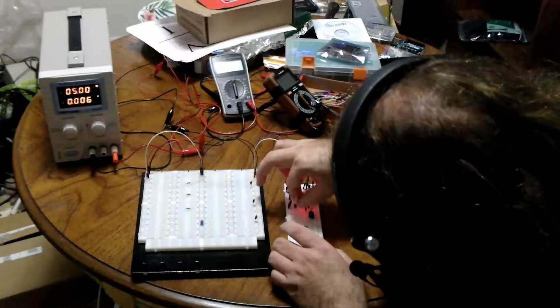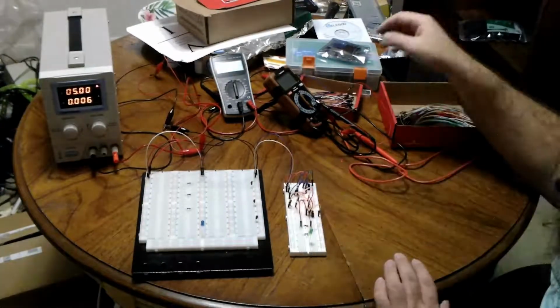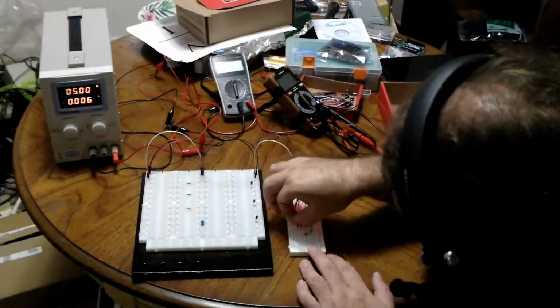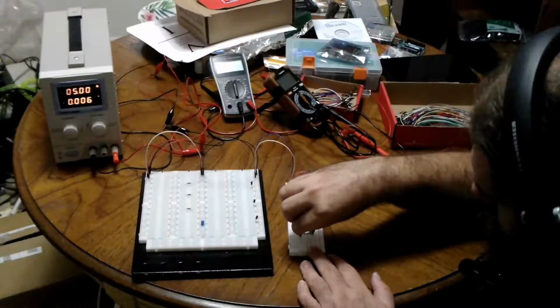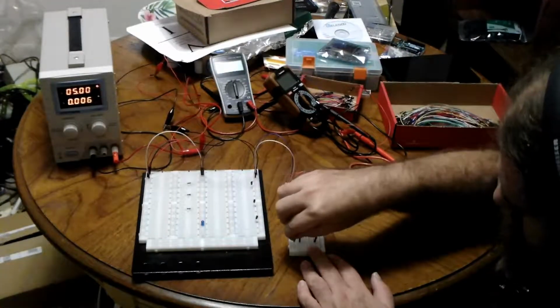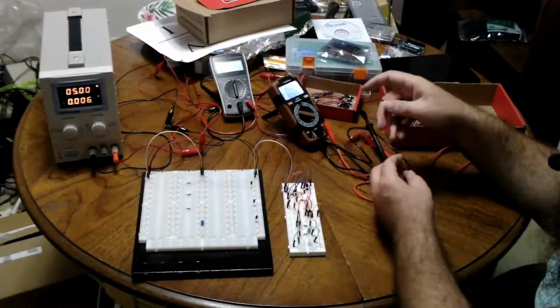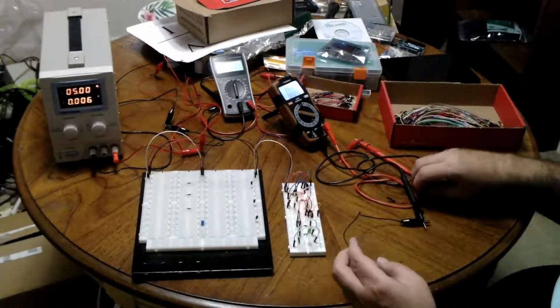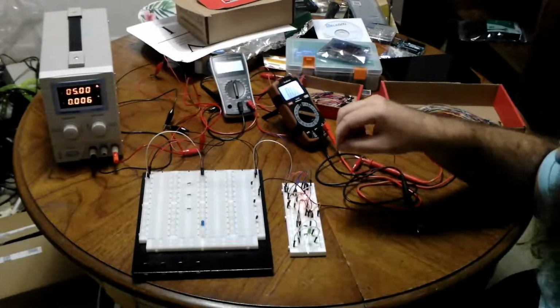So the middle pole of the switch to resistor, out the resistor, to the negative rail, so that'll be input 2, and then over to the second resistor, through the resistor, to the LED, the green one this time, and out. Turn on the switch, and here we go again. I did not directly buy these wires. I got them in a kit. Clearly, there was a cost-saving measure involved, and I'm going to want to actually buy higher quality wires directly.